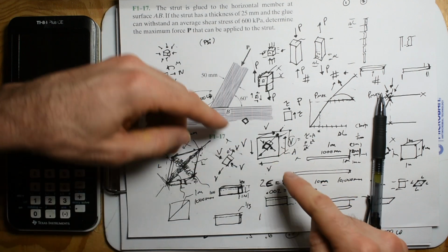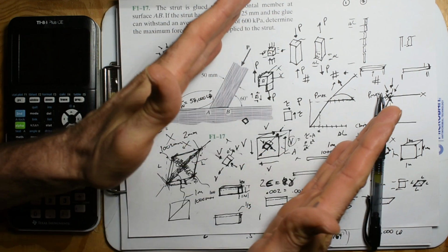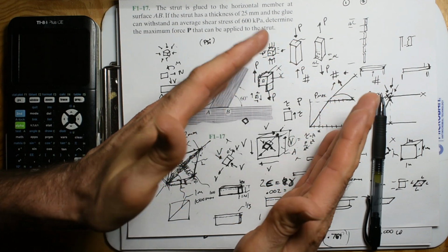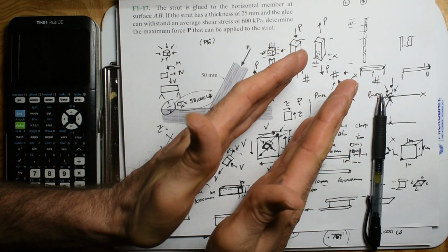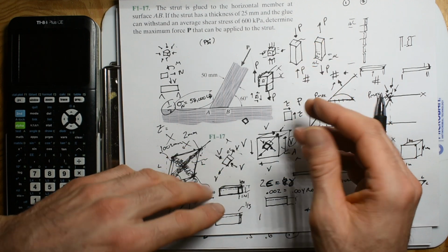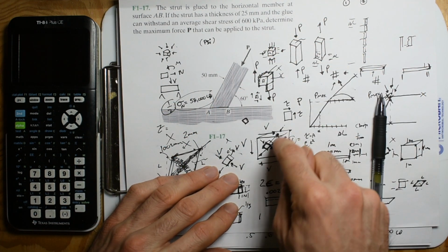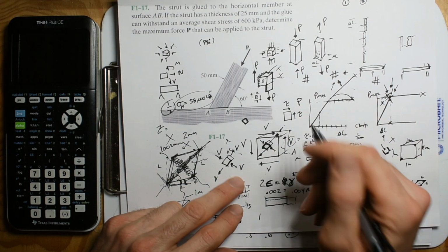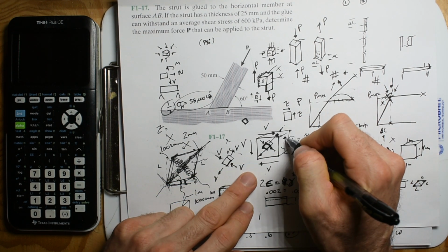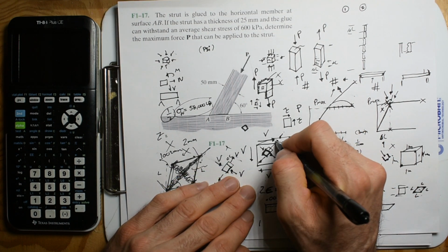So if I'm putting the equal amount of compression on that 45-degree element, then I'm only going 1 millimeter that way. If it squishes out 1 millimeter due to Poisson's ratio, then I can only lengthen it another millimeter. So then the load would be half. Just keep an eye on that.